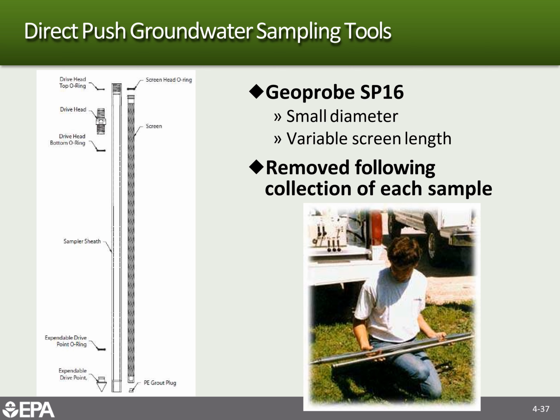This is a separate one here where there's a direct push tool that you push into the ground, and then it exposes a screen that you can then just leave there. I believe they're disposable. No, removed following the collection of each sample. But then that gives you a screen interval for collecting a sample with a peristaltic pump.